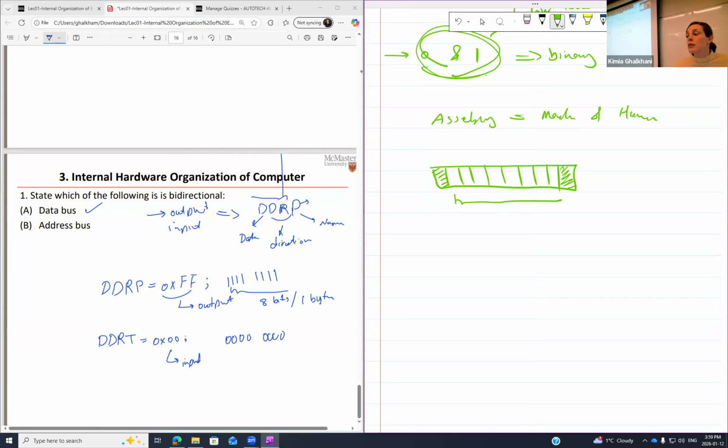And then the rest in the middle, I can bitwise them and put 1, 0, 1, 1, 0, or whatever. But still, I'm bitwising it, means some of them could go on, some stay off, but still LED is always output. It couldn't be both input and output.